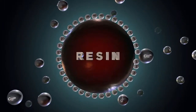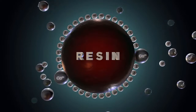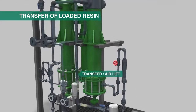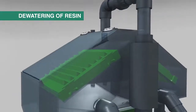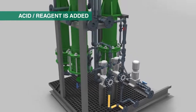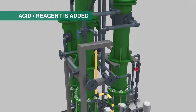Considering the resin chemistry happening on the inside, as we just saw, calcium is exchanged for the loosely held functional group H+, and your resin is then periodically removed from the bottom of your column via pneumatic airlifts. It goes over a dewatering screen into your desorption column, where sulfuric acid is then added to regenerate your resin.